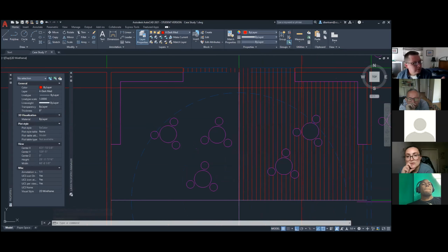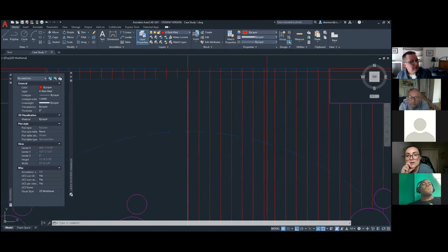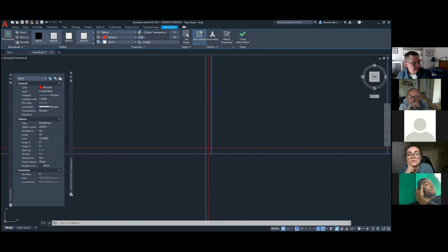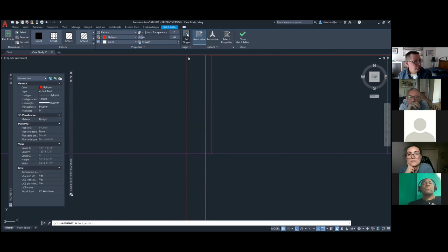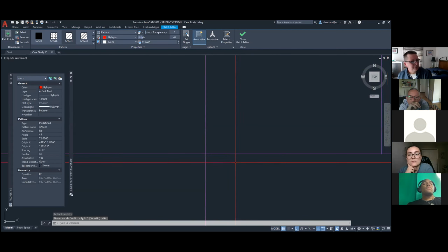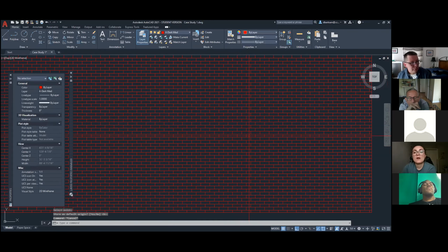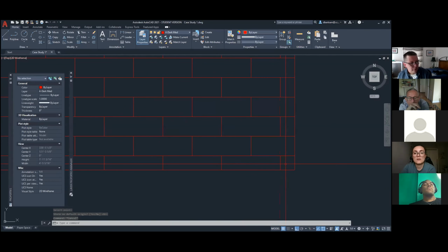Just to make an important point, and it's not that you have to resolve what you were just asking me about, Romina, or anyone else: if the line is not appearing in there, one way to adjust a hatch is to select it and then set the origin here. So if lines aren't starting where you want them to start, let's say this hatch begins, see how close it is right there? If I say set origin to the hatch, now it just moved it. It just started there. And that's why I did this. I don't think I showed you all, but some hatches like bricks are very important because we don't start with half a brick, right?